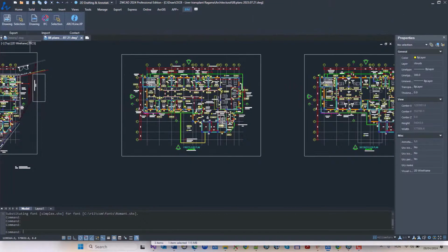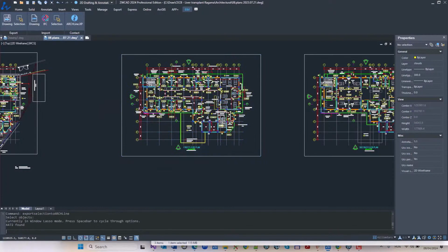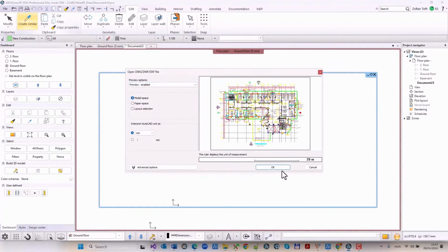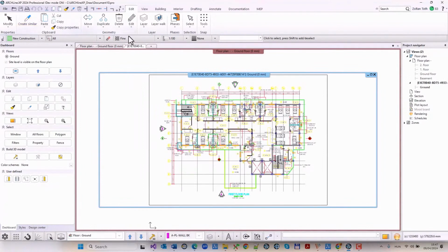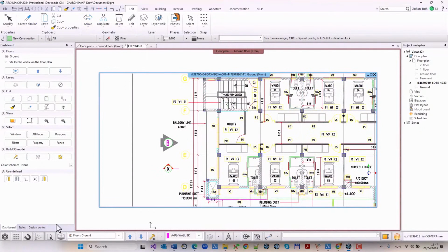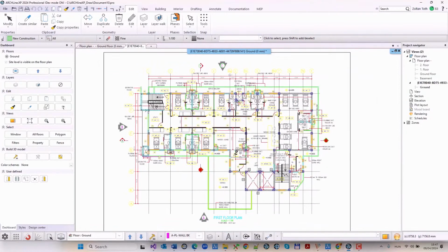The updated plugin allows direct transfer of drawings in DWG or IFC format between ZWCAD24 and ARCHLine XP24 and avoids the tedious import and export task. ZWCAD and ARCHLine XP provide an efficient and effortless CAD BIM solution for those who are familiar with CAD but new to BIM. In this example, I show you how to use the new blueprint feature. You can transfer a selected part of the DWG drawing directly to ARCHLine XP, where you can generate the BIM model from the 2D DWG floor plan.